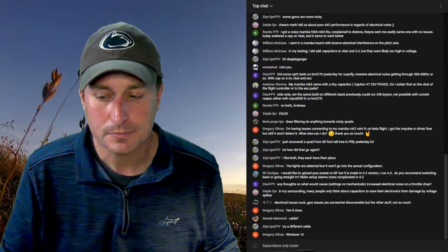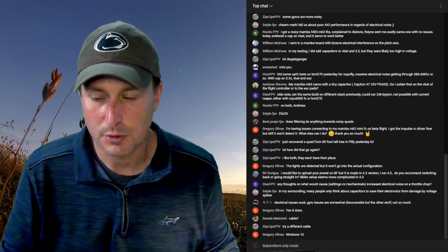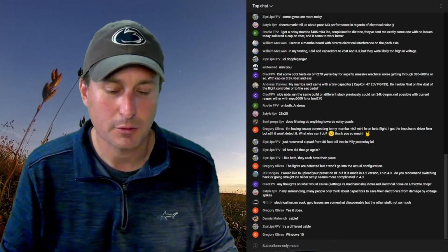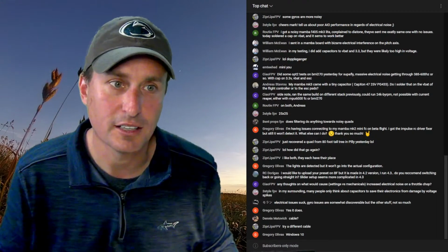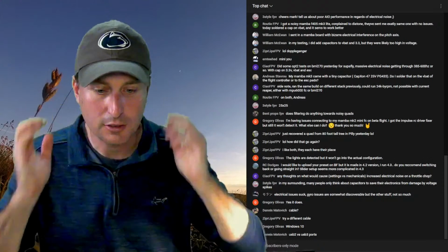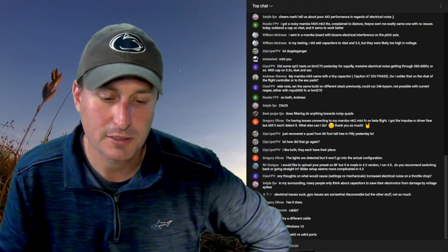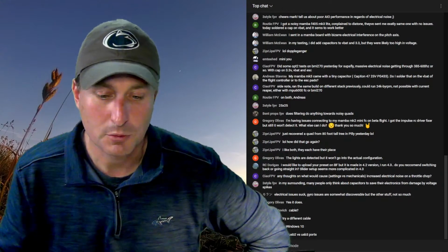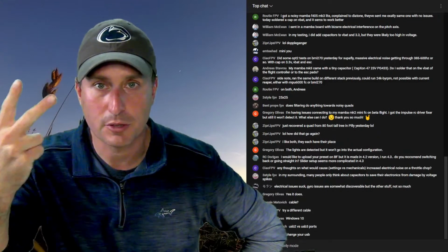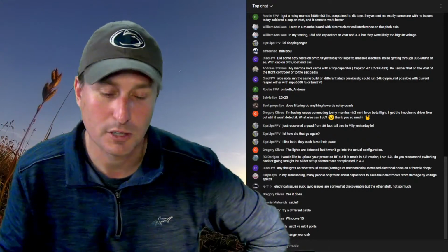If you tried the driver fixer and that did not work, there's really a rabbit hole that I won't be able to get down through here on this live stream, but you can go onto the Discord. I can see if I can help you out with it, and some other guys are on there as well. We can try to work through that, but it can be problematic. So try a couple of things: try a different cable, try to hook it up to a different computer, try to hook another flight controller up to your computer and see if those work.